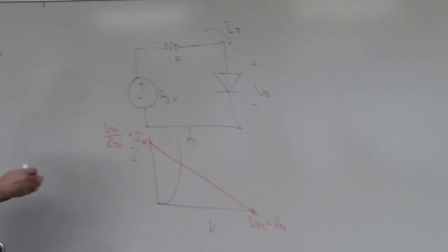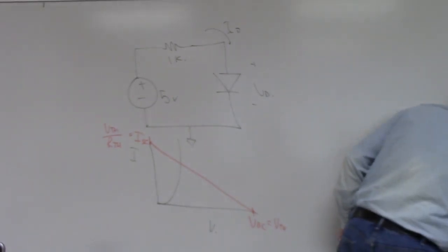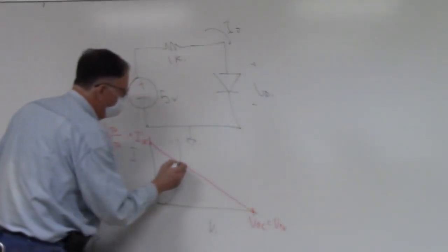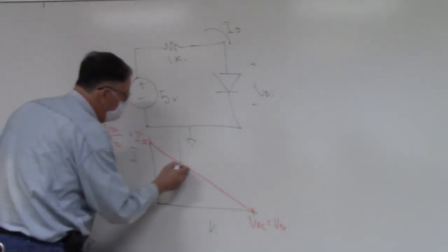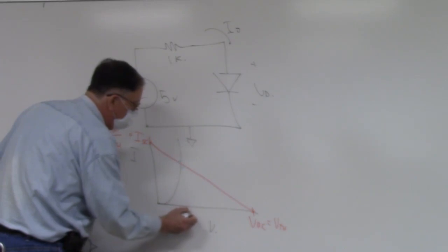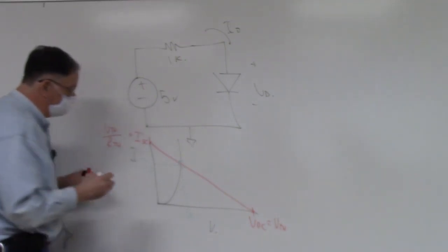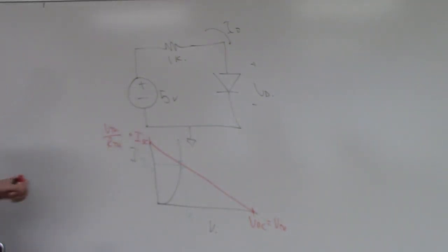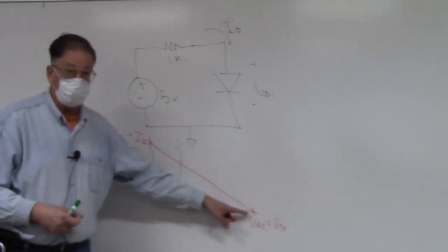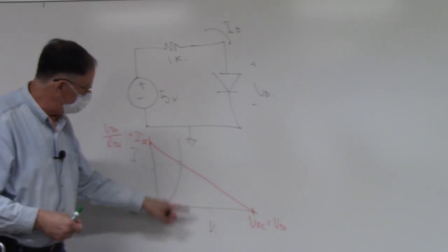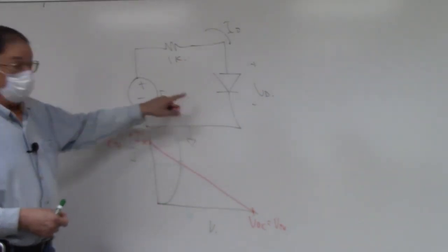And then where the IV characteristic of the Thevenin source meets the IV characteristic of the diode, that is going to be our Q point, right there. So from there, we're going to drop a line down here. That's our V sub D. We're going to drop a line over here. That's our I sub D. And we're going to graphically sketch these. You've already got this curve. This one you can sketch right on top of the graph. Where they meet, measure that, and then compare those with what you get when you have this circuit.